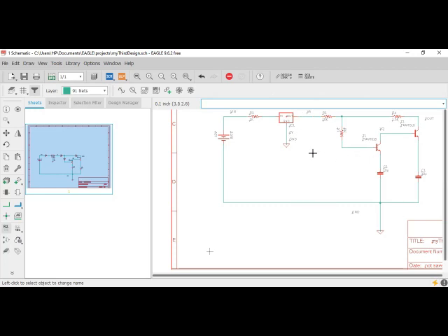So after labeling, the next thing is to add a voltage probe to them. So let's add a voltage probe here. Our voltage probe is V in because you have labeled it. It's going to do it by itself, V in. So now if you add a voltage probe here as well, it's going to bring it out for you.